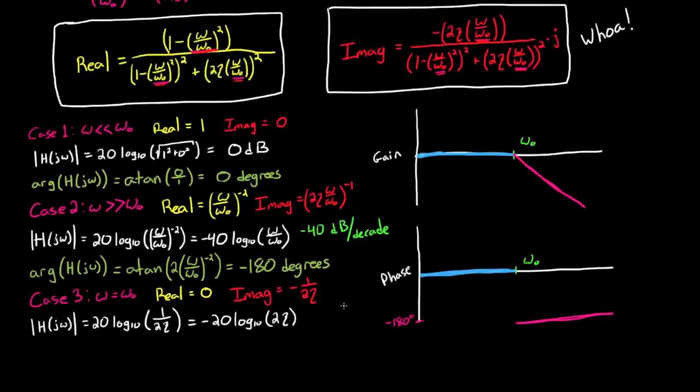In other words, as your damping ratio decreases, your magnitude at this break frequency increases all the way up to infinity when zeta goes to 0. Notice that for zetas larger than 0.5, this magnitude is going to be less than 0. For that reason, for the approximation, we generally only draw a peak when zeta is less than 0.5.